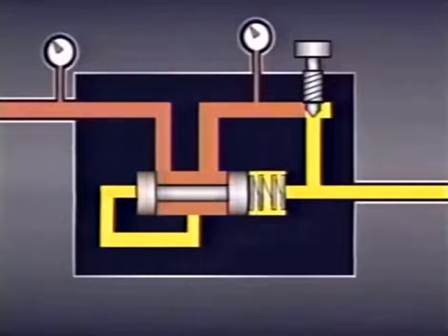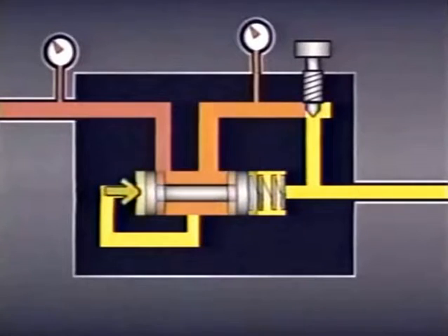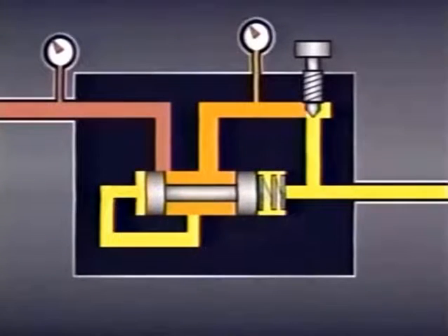For instance, suppose the valve has a 100 psi spring and inlet pressure is 500 psi. In operation, pilot pressure will push the spool over until pressure downstream of the restriction created by the spool is reduced to 100 psi, the tension pressure of the spring. The remaining 400 psi is converted into heat and carried away by the fluid.